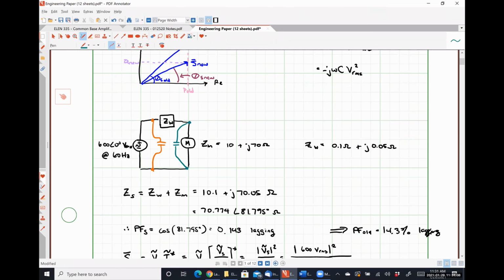And so my student asked, why would you ever do one versus the other? And it's purely from a cost perspective, right? So for instance, if you only have a few loads that are screwing up your power factor, it may be reasonably cost effective to just correct at those specific loads.